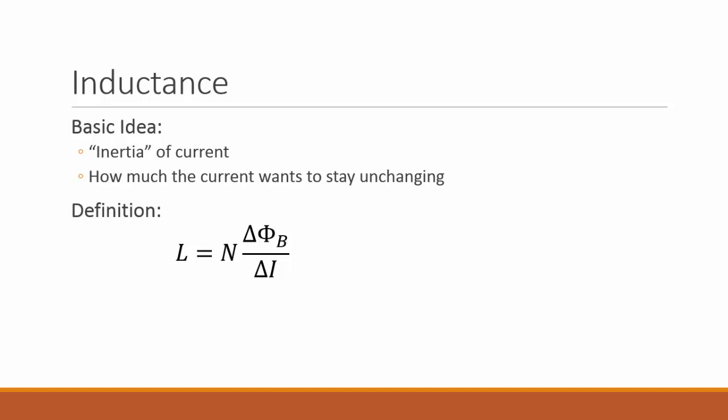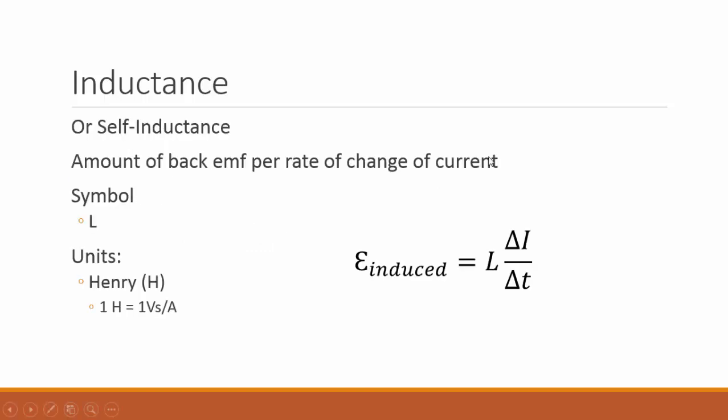The definition that they'll give for inductance, which is actually related to that previous ratio here. So one way you can think about it is it's this proportionality constant. That for a given circuit, if you have a certain number of amps per second changing, that'll produce a certain amount of voltage. If it's twice as many amps per second, then you have twice as much induced. And the proportionality constant is the inductance.